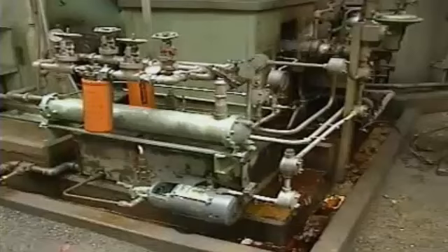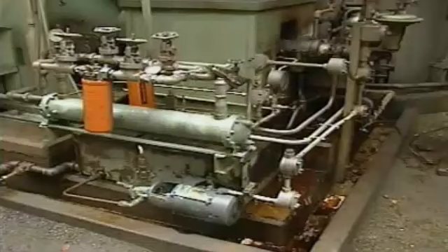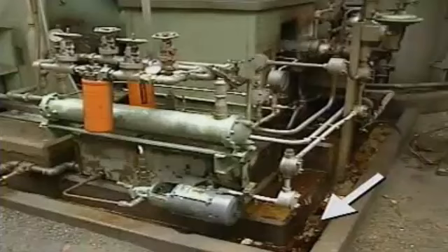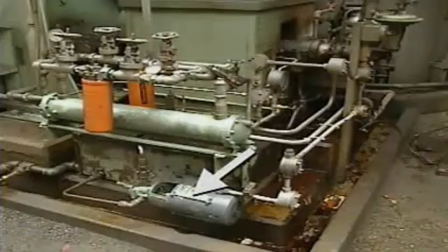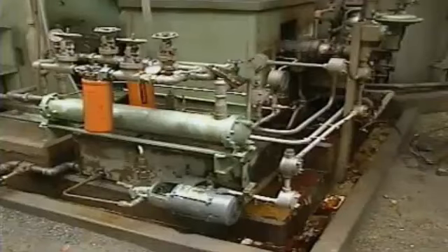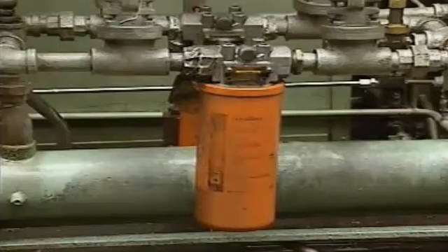Another type of oil lubrication system for sliding surface bearings is a force feed system. This type of lubrication system is used when a pressurized feed to the bearing is required or when it is necessary to keep the oil filtered and cool. In a typical force feed system, oil is stored in a reservoir that is separate from the bearing. A pump forces the oil into the bearing. After the oil has passed through the bearing, it is collected in the reservoir so that it can be pumped again. Oil filters are often used in force feed systems to keep the oil clean.